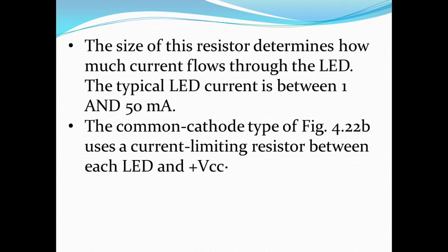The size of this resistor determines how much current flows through the LED. The typical LED current is between 1 milliampere and 50 milliampere.